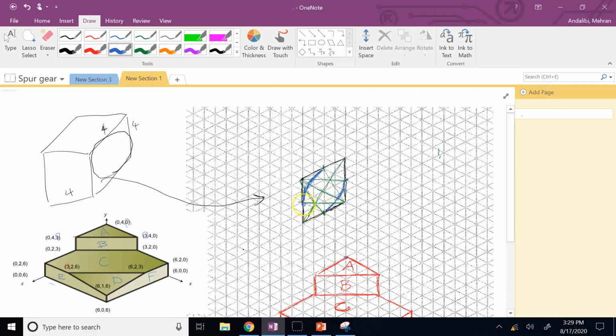Then put it at this focal point and use this smaller radius here. And then on this focal point and that radius, or this one. And that's your ellipse, okay? And you can get rid of these green lines because you don't need them anymore.